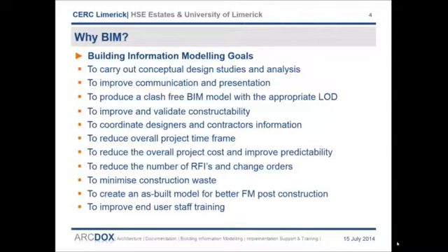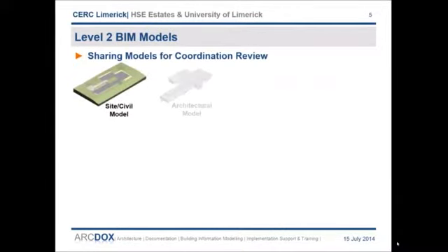The reason the client and design team are asking for BIM is that they want to improve communication, understanding and the flow of information on the project. They want to try and identify any issues early on in the virtual model and resolve these before carrying out the work on site. These could be design coordination issues or clashes, buildability or sequence issues, logistics and health and safety issues. The ultimate aim is to reduce the risk for all parties on the project and avoid unnecessary cost, overruns or delays. The project will be carried out to Level 2 BIM.